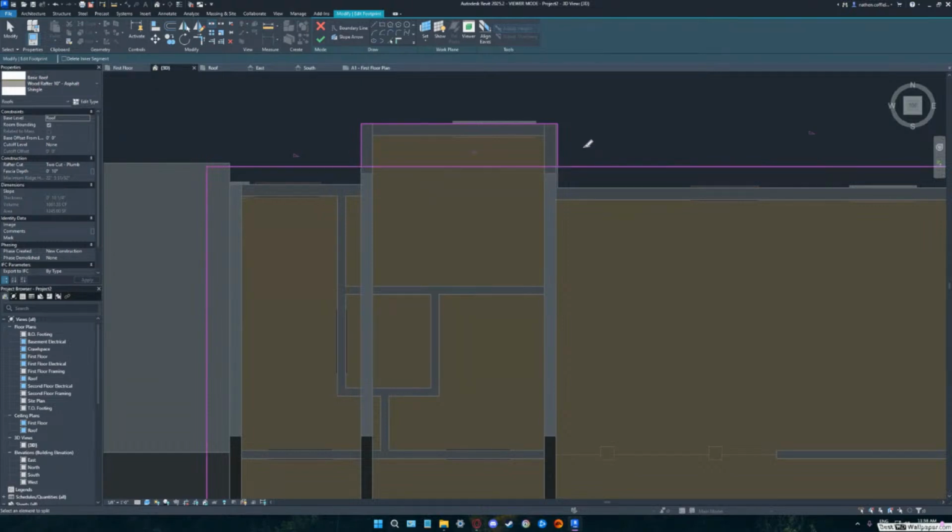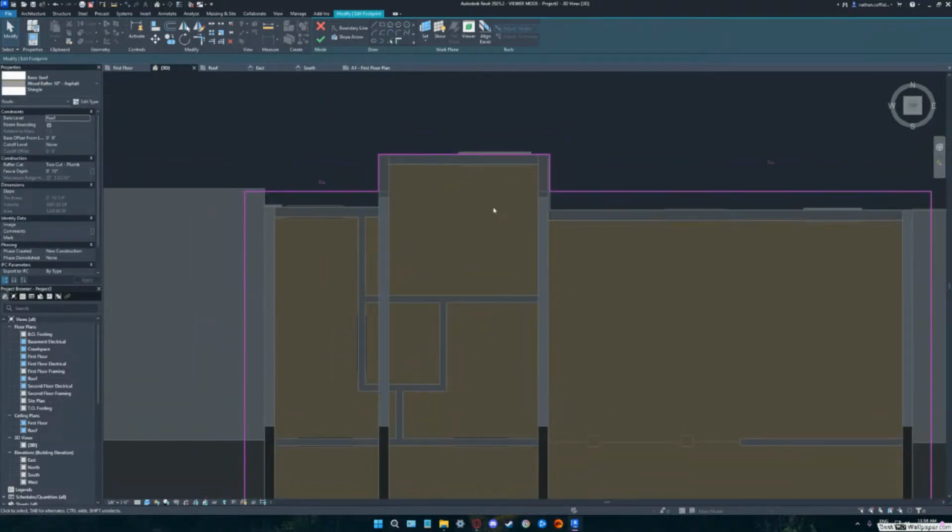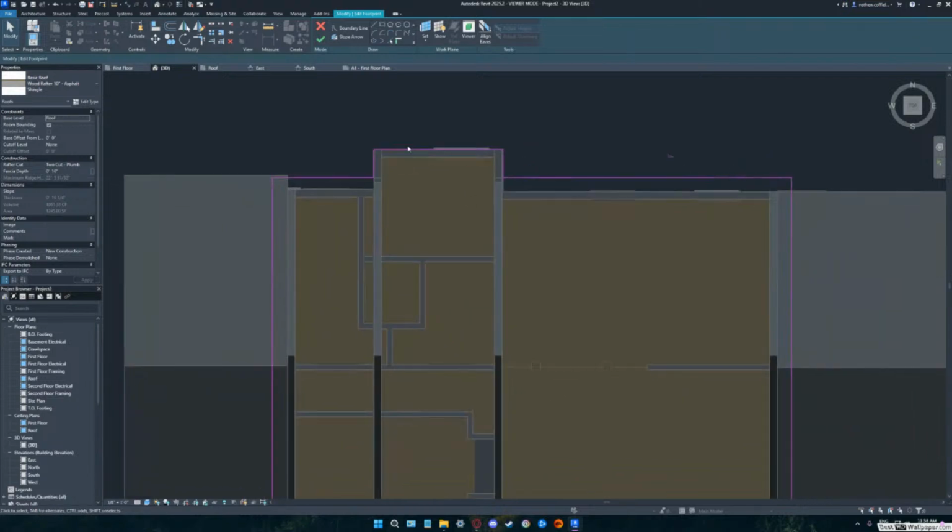Perfect. Now delete that, escape 2 times. Delete that centerpiece. Nope, down. That one, yep. And now, just to help Revit, you see how both of those lines along that back edge have a defined slope? Take one of those defined slopes off. It doesn't matter which one. Pick that, take the defined slope off. And if you now finish, it's going to work.